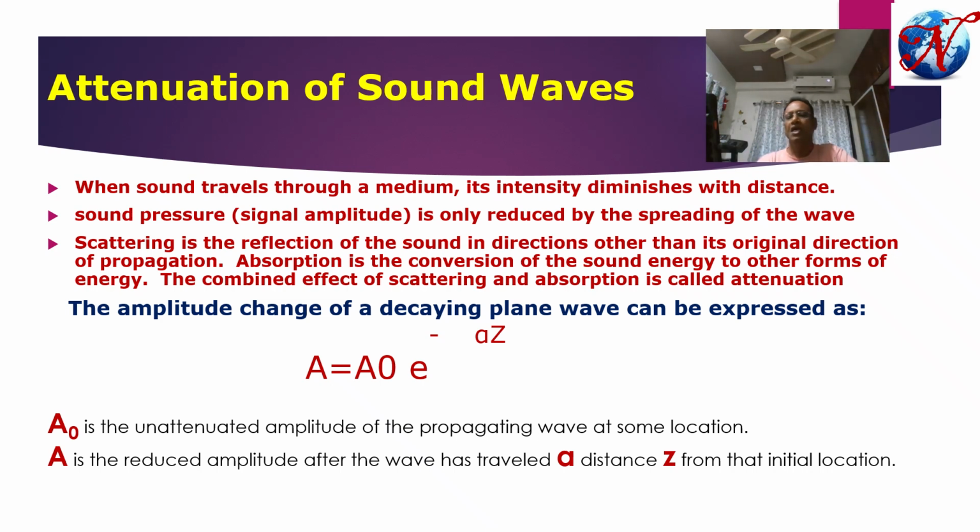For example, the normal or TR probe comes in different crystal diameters like 5 mm square, 10 mm square, and 25 mm square. Depending upon the penetration thickness required and the grain structure of the material, the code suggests the selection of the diameter such that near field and beam spread will be under control.